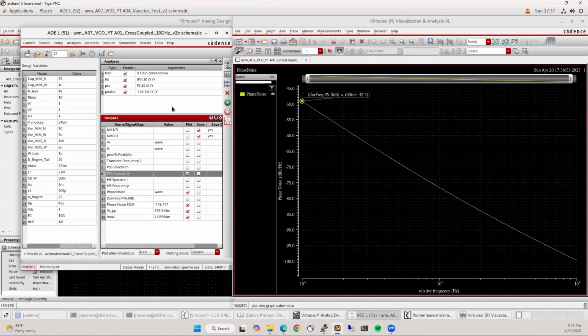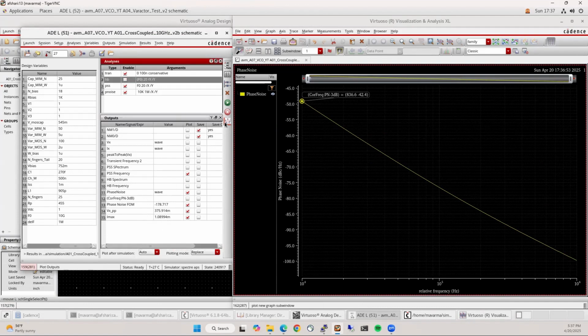Problem, however, is that the PSS frequency, we can actually turn off HB, we don't need that, is around 8.9 gigahertz. So right now everything is off, right? So when everything is off, it should be very high. Actually, it should be around 11, whereas it's around 9 gigahertz. And that's because I told you that the capacitance is much larger, right? Because of the capacitances of the varactor now. So to compensate that, we will reduce this to around maybe 680 pico.